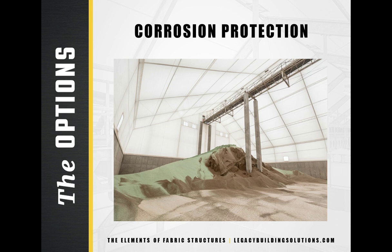A vital step in corrosion protection is hot dip galvanizing the steel framing members. Every steel component, from the I-beam framing members to screws and fasteners, should be treated with hot dip galvanizing during construction. For the ultimate in corrosion protection, a fabric liner provides a continuous barrier between the corrosive material and the steel. Even the fine dust and particles are kept off the steel.